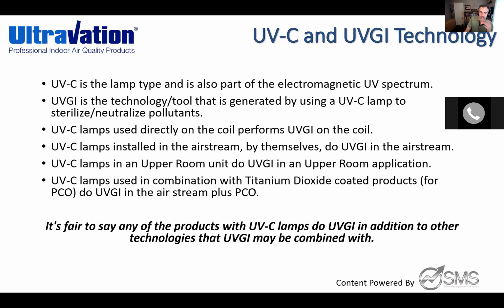The last bullet point here is that you can also apply other technologies. Once I've accomplished UVGI, I'm aligned with ASHRAE standards. When some of my products are upgraded with titanium dioxide coatings and doing PCO, now I'm applying that as well. But at the foundation, we should be applying UVGI technology using UVC wavelength bulbs.